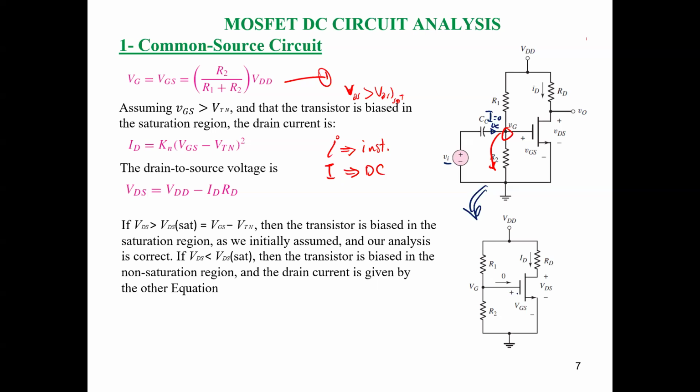Why do we have zero current, guys? Actually, this is the steady state operation. For any kind of MOSFET, you already have the gate, with the oxide right after it, so it's already a capacitor. The DC current will be zero as well.